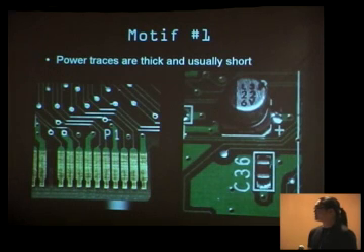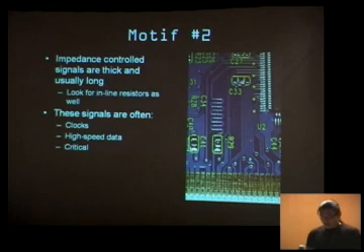Why? Because it's easy to just make all the signal traces the same size, and the guy actually has to apply effort to make thick traces, right? And you want power traces to be big and fat, so those are power traces. Same here. These filled regions here are power traces. You can see they're connected to vias. This guy's ground. I don't even have to pull a probe. I know this is the ground plane. That connection is ground. That connection is power. Done. Here on this capacitor, you see this plus sign here. That's power. That's ground. Done. Right. So I didn't have to trace it out.